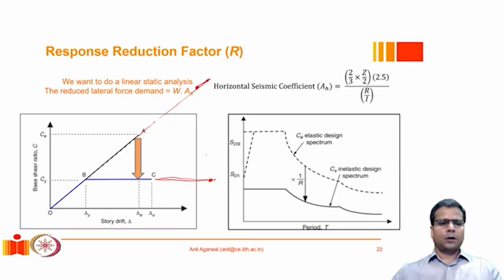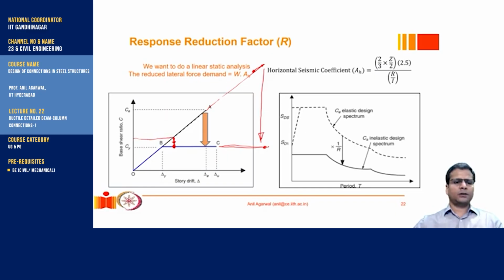In such a scenario, we can utilize a response reduction of up to this level. Whereas if the system is not very ductile, and at maximum we can utilize only this much yielding or this much permanent deformation, my response reduction would be only this much. So this factor, with respect to the elastic force that we would calculate here, this response R factor would be very large in comparison to this R, and that is definitely a function of how much ductility is available in the system.